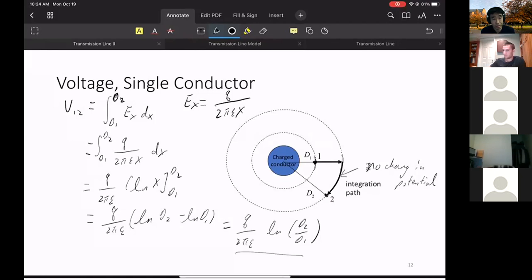called was between transformer 1 and transformer 2. Then they found that impedance per unit, and the per unit impedance of the load. And then they said the equivalent circuit was just those two things and the generator in a circuit, and they left out any impedances in the transformers. I was really confused why they did that and how they could call that an equivalent circuit.